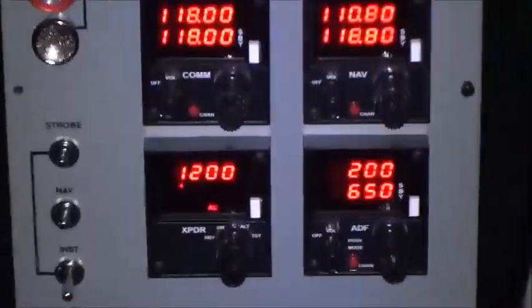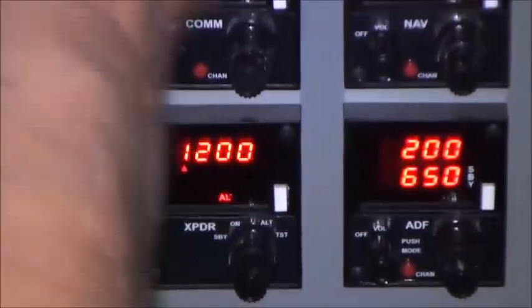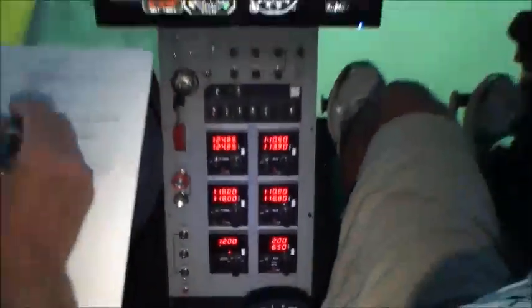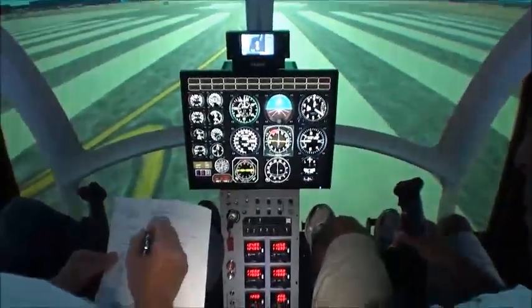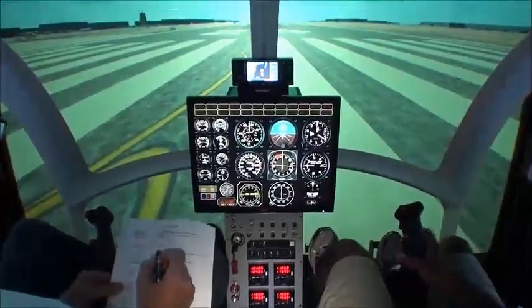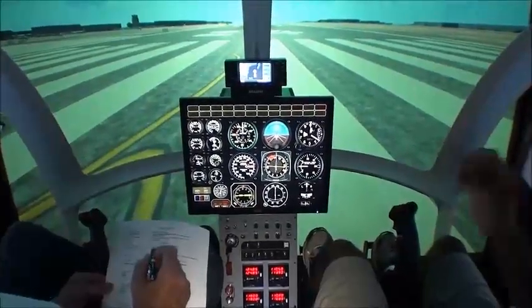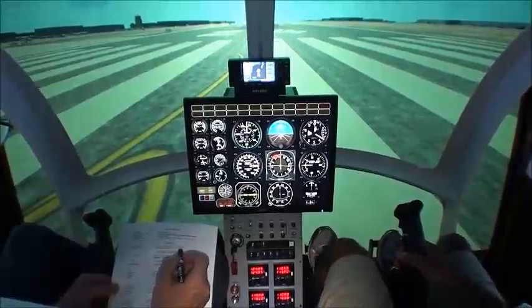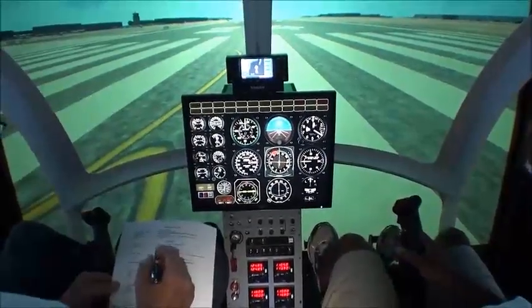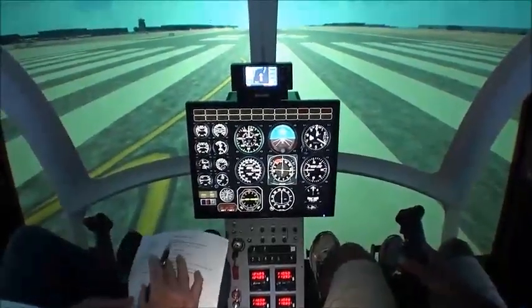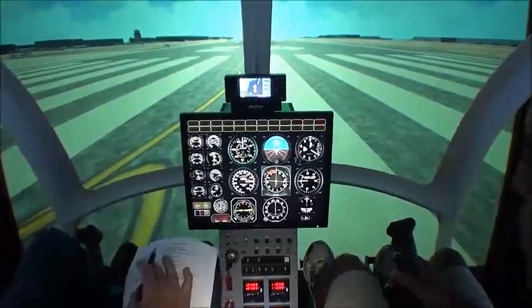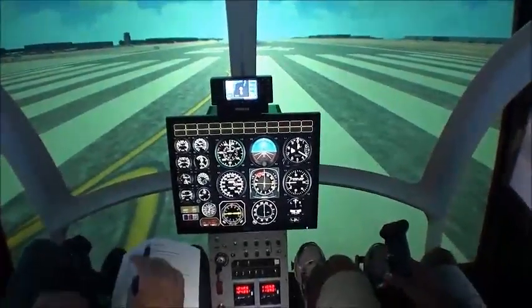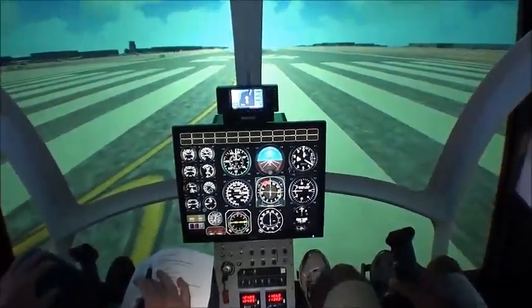Okay. Lights as required. We got our strobes on, check. Okay, that's before takeoff. So for takeoff, the checklist says collective pitch to hover, observe TOT and torque limit, and direction control with the cyclic as required. So before takeoff is complete. There we go. You're cleared to take off.